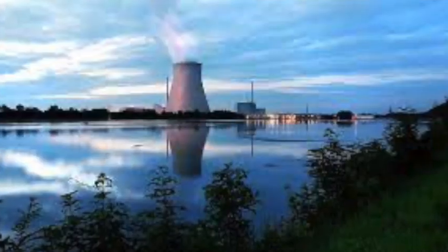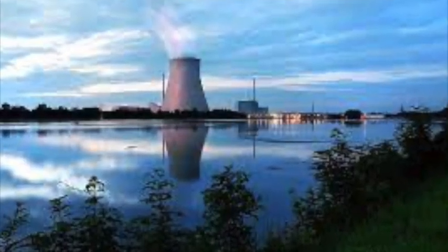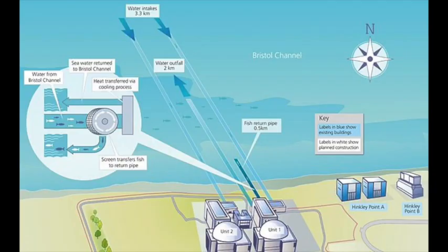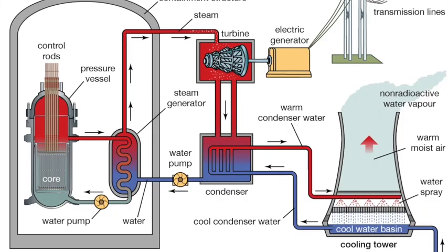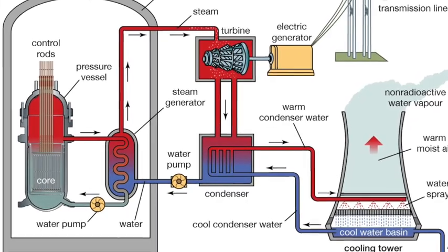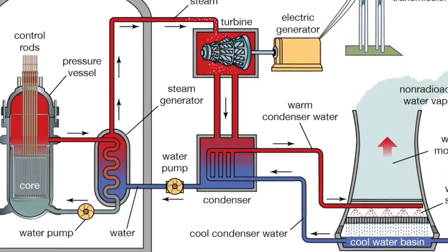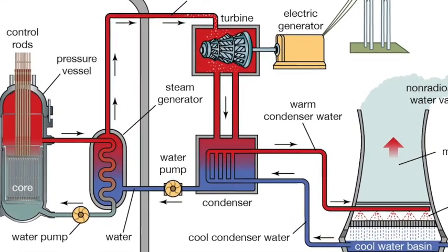There are two general ways through which water can be returned to sources from nuclear power plants. The first is when it is directly returned to the rivers and lakes that it is taken from. This has some ecological downsides because it can potentially raise the temperature of the water it is returned to. The second is when the water is cooled down by a different set of water, and the internal tank is then recycled for later nuclear processing. This has a lower water count than the first option.